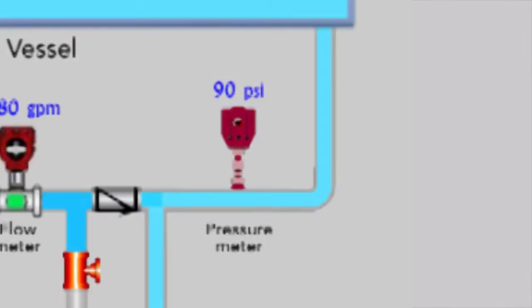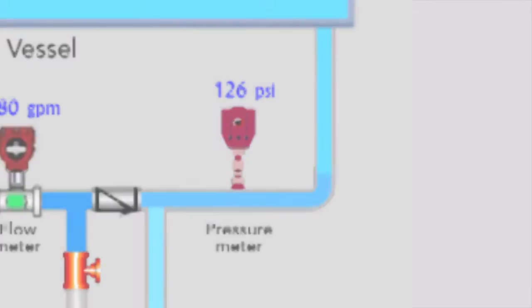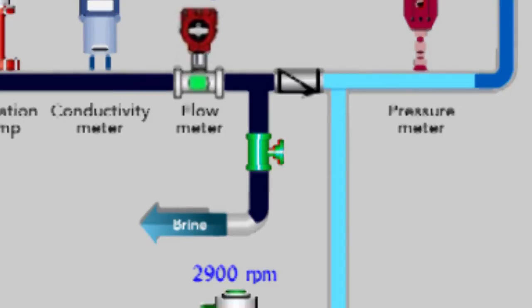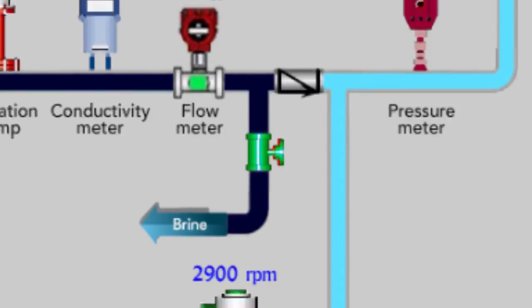Each batch in the CCD process starts at a low feed pressure, and this increases as salts accumulate in the system. The average membrane feed pressure is much lower than the feed pressure of typical RO systems. Lower feed pressure means lower pump energy requirements and tremendous energy savings. CCD systems also dramatically reduce energy loss to the brine reject stream by reducing its pressure prior to release.